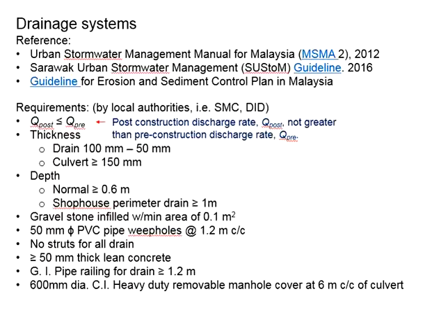You as the designer, or considering on behalf of the developer, your intention is to minimize the cost for the constructions. This is so that you can maximize your profit. However, the local authorities are more concerned with the public safety as well as the long-term maintenance. Nowadays, even for the open drain, during the submissions, they have the requirements not to use mild steel wire mesh as the reinforcement. Instead, they will require double layers of reinforcement for all drains.